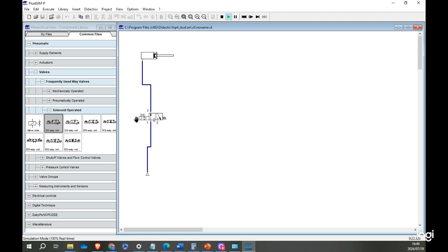If you release the button, the spring inside the cylinder will automatically retract our piston rod. Another thing to observe is the dark blue color and the light blue color. The dark blue color means this is our air coming from our compressor. But as I said, this is a normally closed two-way solenoid valve, and it doesn't automatically release our air into our cylinder.